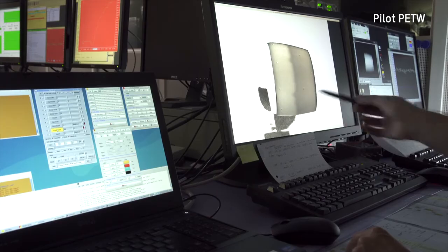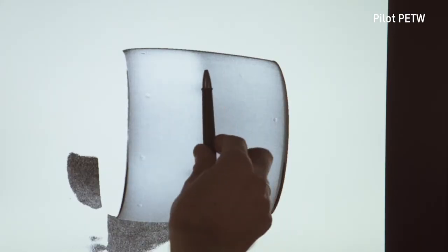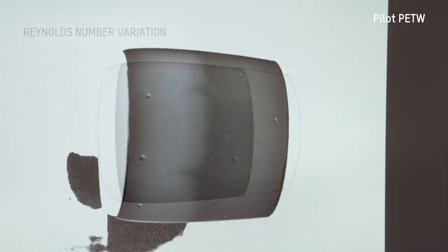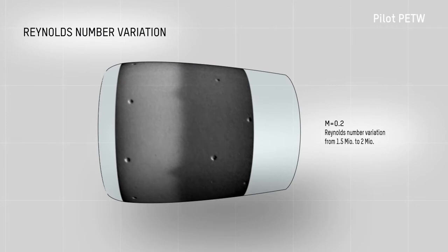Accordingly, parametric studies with continuously changing angle of attack are now feasible, which is significantly more efficient than the temperature step method. The continuous TSP method is a very powerful tool for test engineers and researchers in order to optimize the wing shape and aircraft geometry. Physical flow phenomena can be studied experimentally to enhance understanding and to enable validation of numerical simulations.